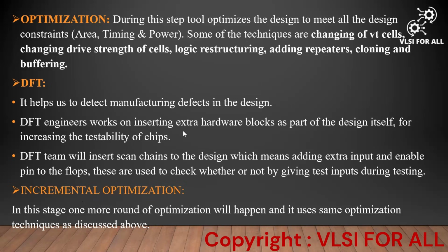So DFT engineers work on instantiating extra hardware blocks as part of the design itself for increasing the testability of the chips. The next one is that the DFT team will insert scan chains into the design, which means adding an extra input and enable pin to the flops. These are used to check, by giving test inputs during testing, whether manufacturing defects are there or not. With the help of scan chains, it will test.